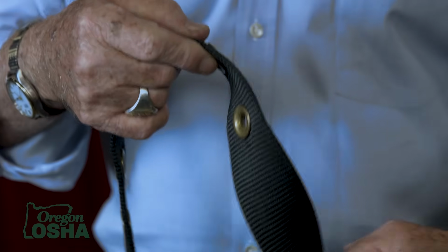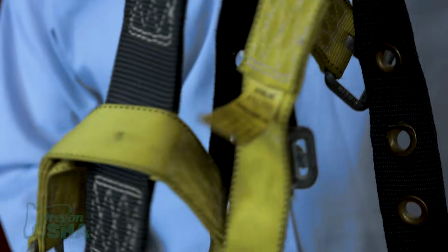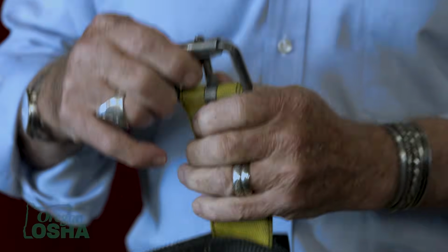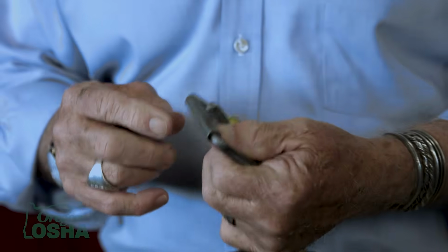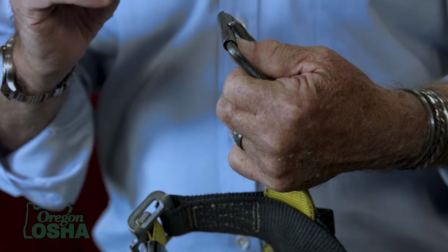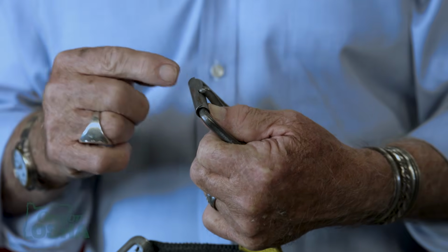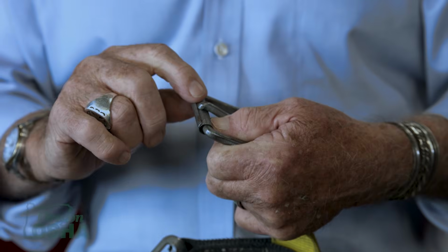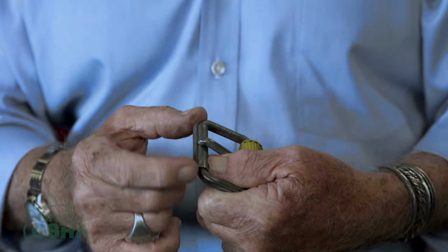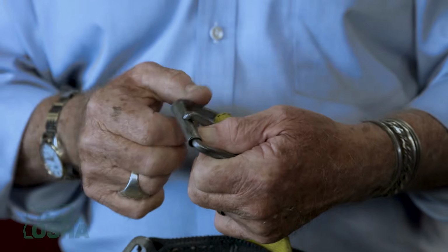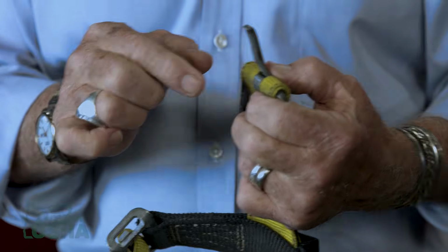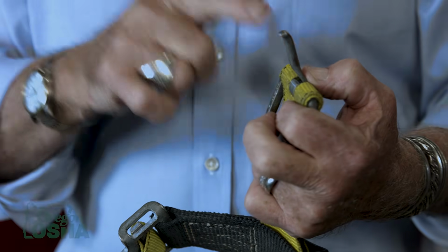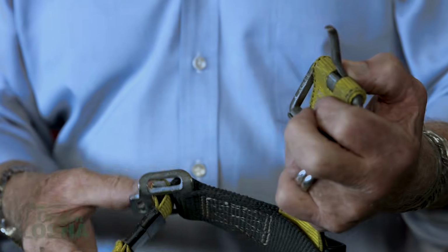Check and make sure that the buckles that these run through are round. So you'll notice that this buckle and its mate have that same type of protector between fabric and metal designed to roll. So a roller buckle, once impacted, the metal will come out of round and it'll simply overlap itself. You'll also change the spindle, but it's easier to look at that part than it is this part to determine what's wrong. Down on this end, we pay particular attention to the groin straps.